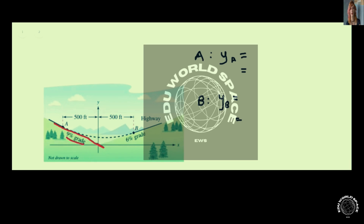Now the hill is going in the downhill direction, so we know that the slope is negative. So the tangent slope would be negative 0.09, and since this is with respect to x, it's just negative 0.09x. To find the coordinate at point A, we can see on the diagram that it is 500 feet out, so 500 feet is our x value. So we simply plug in negative 500 for point A since we're to the left of the y-axis, and when you plug that in, you'll get that y sub A equals 45.